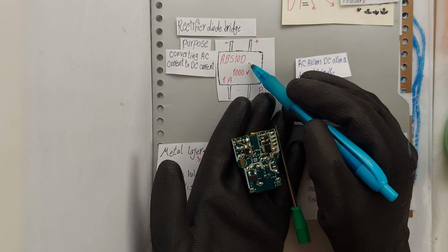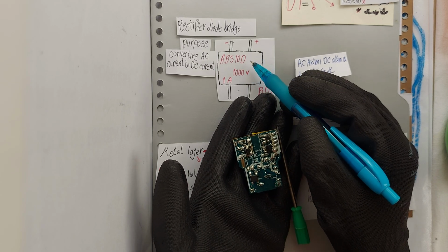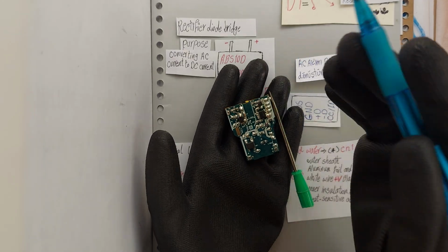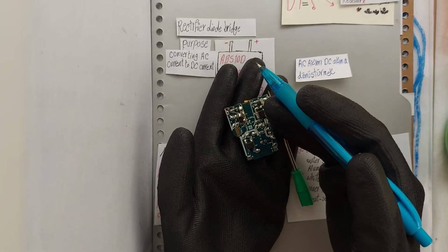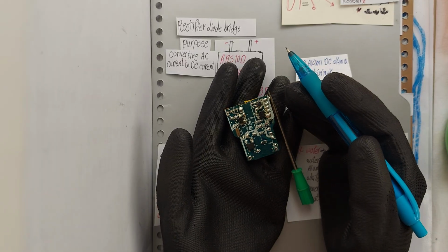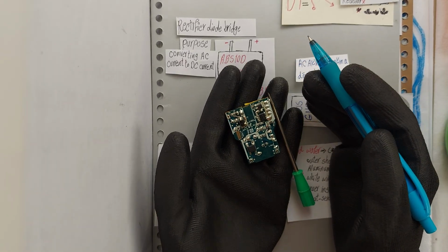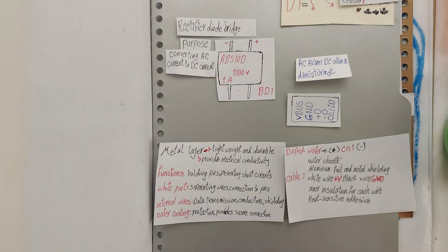The D in ABS10D is likely a manufacturer suffix, for example for packaging or protection code, and doesn't affect electrical performance. After the AC passes to the fuse and filter, it produces an approximate 320 volts DC peak input voltage.